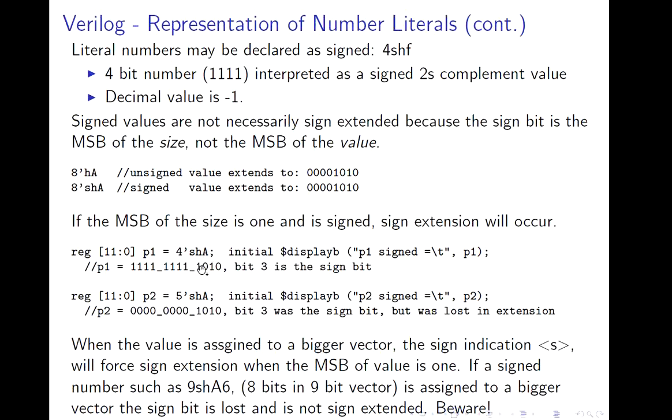So first I'll write the value of A. A is 1010, hence 4 bits, and it is going to be stored in a 12-bit register. Since it is represented as signed, you extend the number with the last bit and make it a 12-bit number. And then you see over here, what is the last digit? It's a 1 and it indicates a negative value of this particular A. So that's how the extension works. Here also I did the same thing.